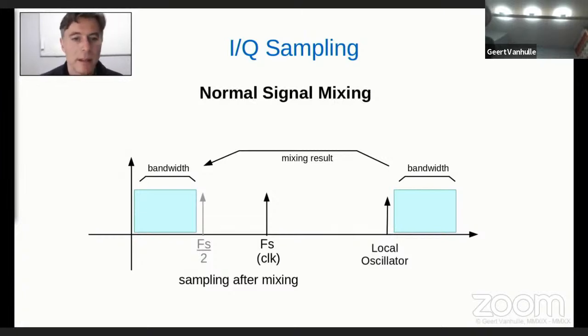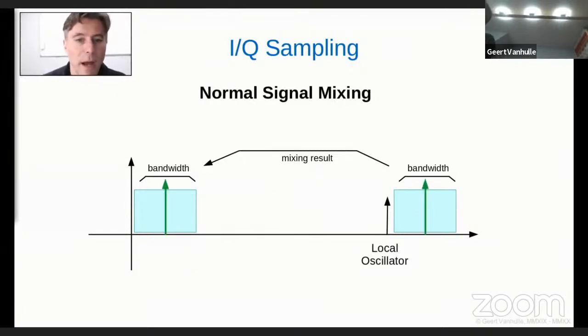The bandwidth is the whole stage from 0 up to half the sample frequency. This is going to be our first Nyquist zone. That will be our zone of interest. Now, if we have a random carrier in this bandwidth of interest, it will be transposed into our baseband at this location.